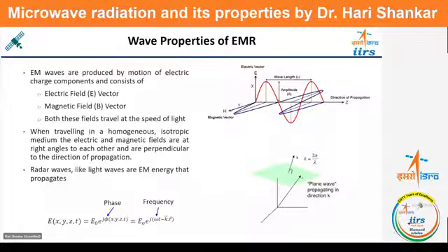So you can say the interferometry is applied whenever we are interested in the motion of the target, or we want to analyze the motion of the targets on the surface. Okay, so there are various examples of this very slow motion. I'm talking about few millimeter or centimeter per year. This is not like the movement of your aircraft or movement of your car. That is very fast. Those types of motion you cannot analyze with the help of the SAR images, because those are very fast movement. Here we are talking about very slow type of motion.